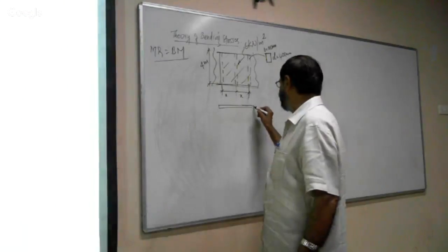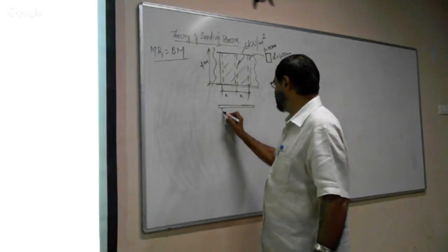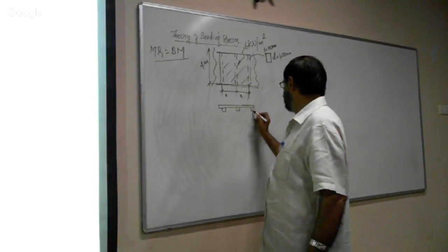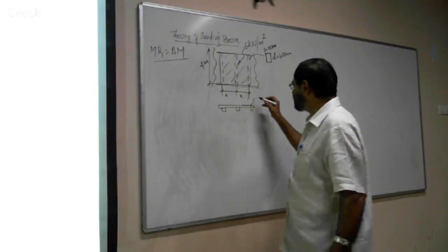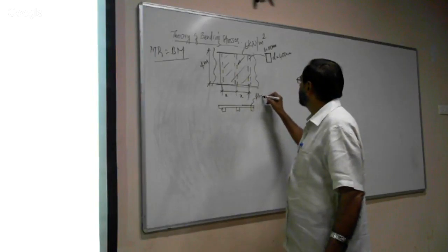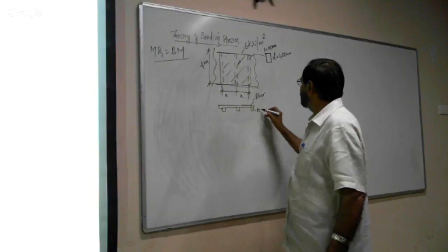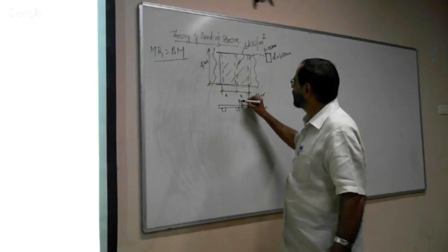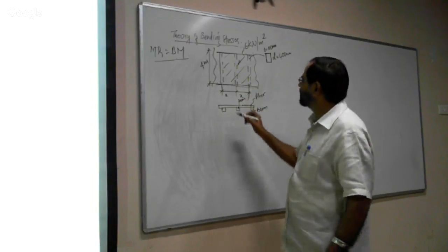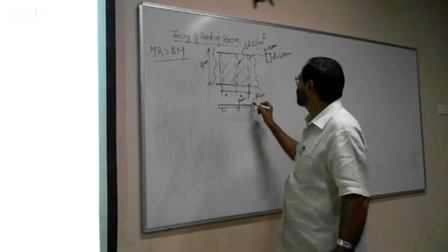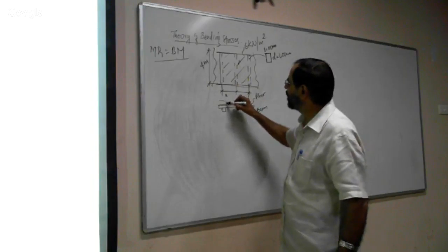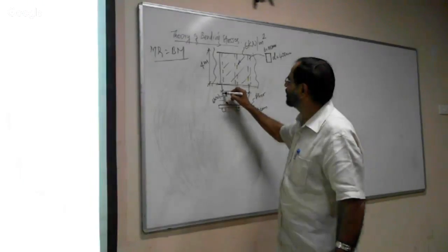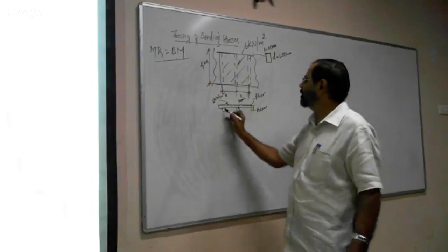The floor is like this, and the beams are placed. Now these are the beams. So this is the floor. Now please understand the problem. It is the floor, and these are the beams. Now this is a beam. It is subjected to a load of floor area over the floor. It is 6 kilonewton per meter square. Now this is the beam given, the beam size.